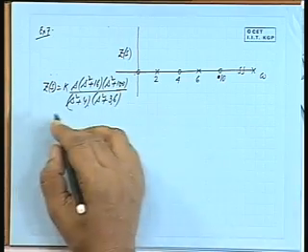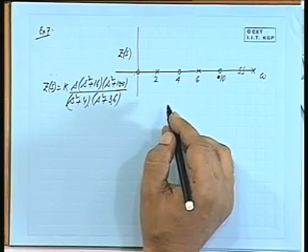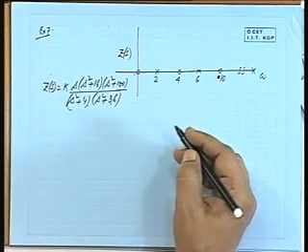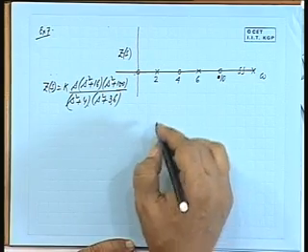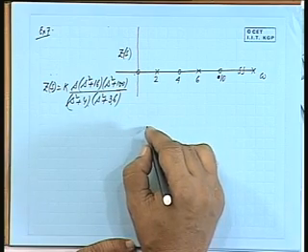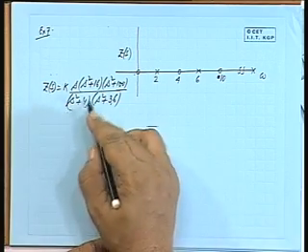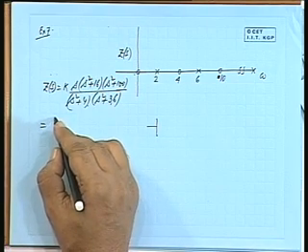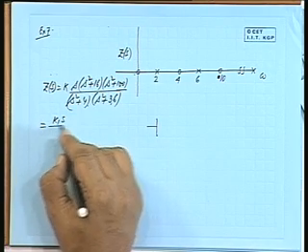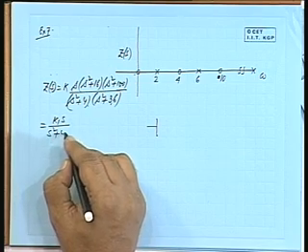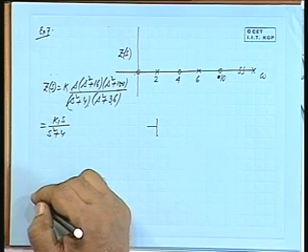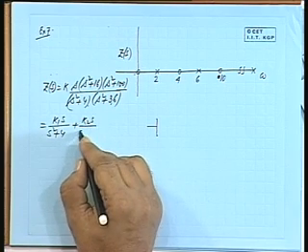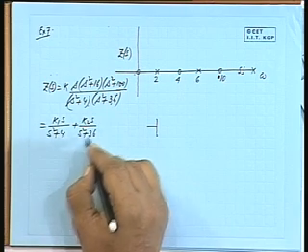Okay, and if I ask you to get Foster 1 synthesis, you can do this. All right. So what will the Foster 1 structure be like? S squared plus 4 will be one pole, so that will give me something like K1s by S squared plus 4, plus K2S by S squared plus 36.